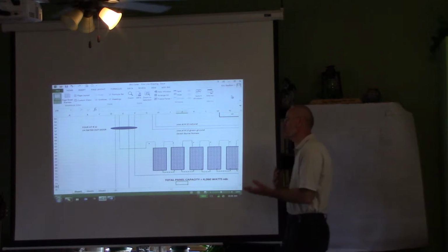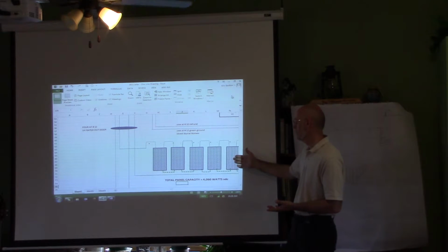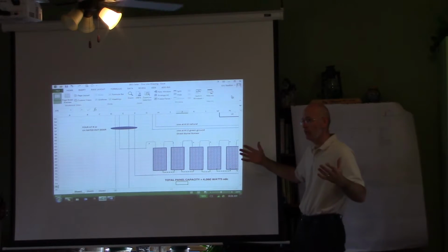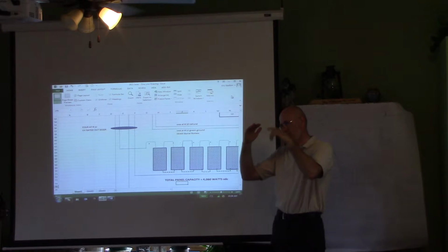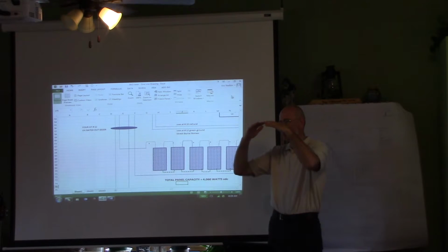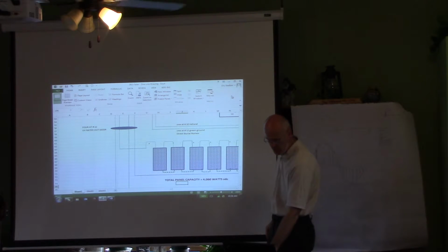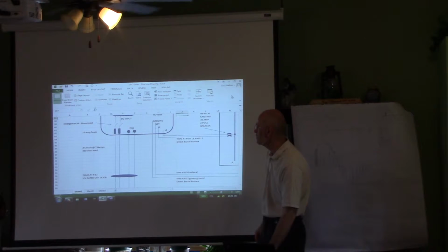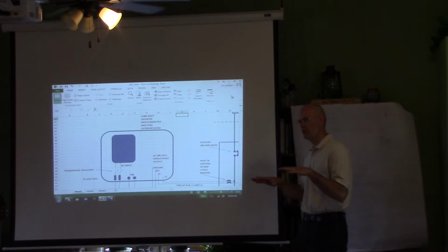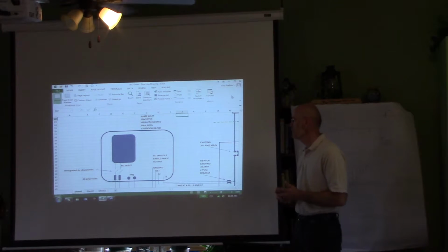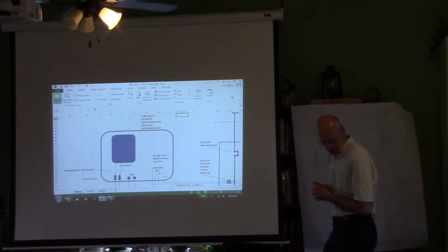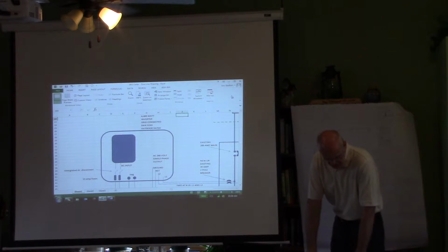It does have the advantage though, because in low angle sun, where you're not right at it, you'll be producing more power during those shoulder hours of the sun, morning till evening. You'd be producing more power over here and here, but when you get to the peak of the day, you're really pushing your inverter to dissipate that heat. And you could overdrive it. So you want to be, like I said, 20% less than your nominal inverter size, because on those cold, sunny days, you'll be right up to the peak. Are there any questions?